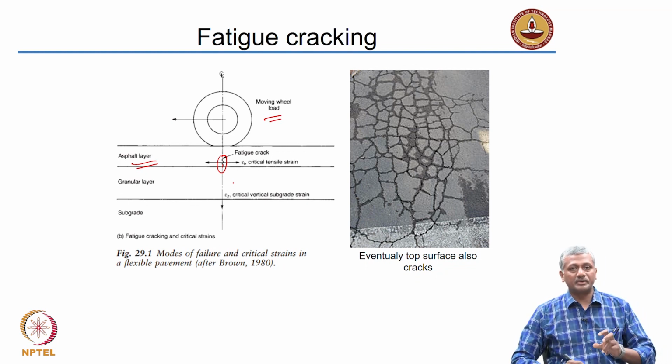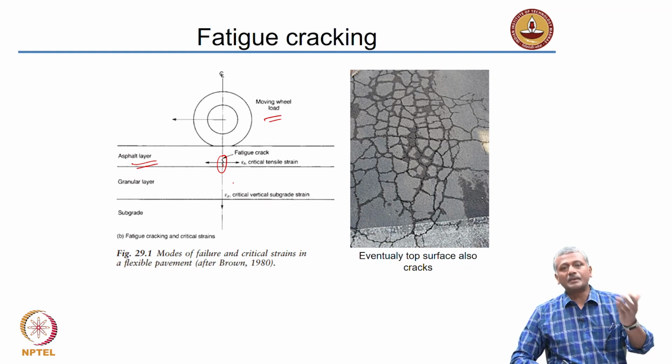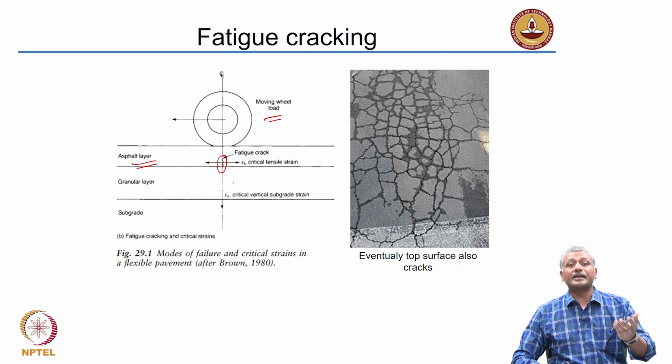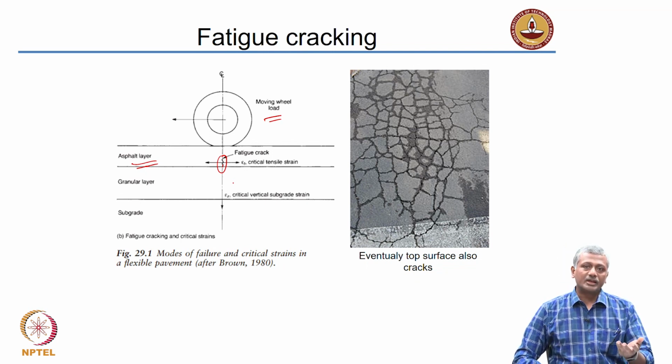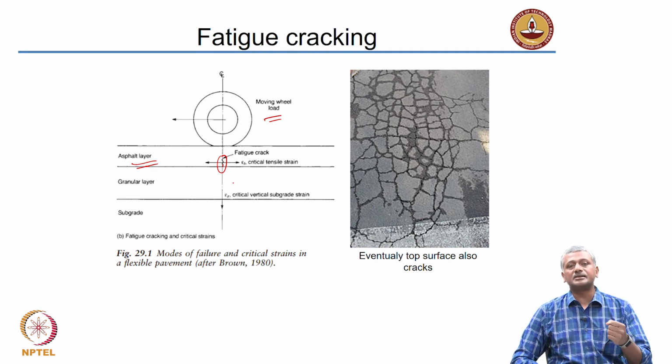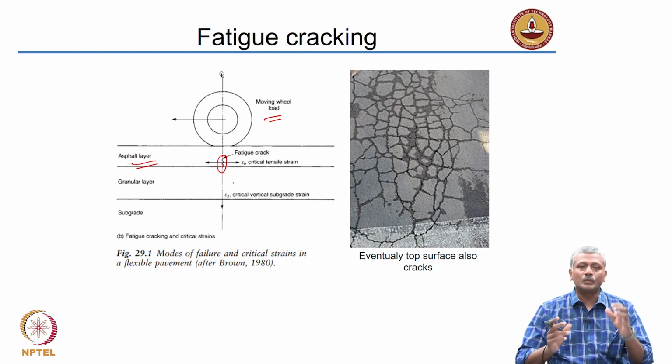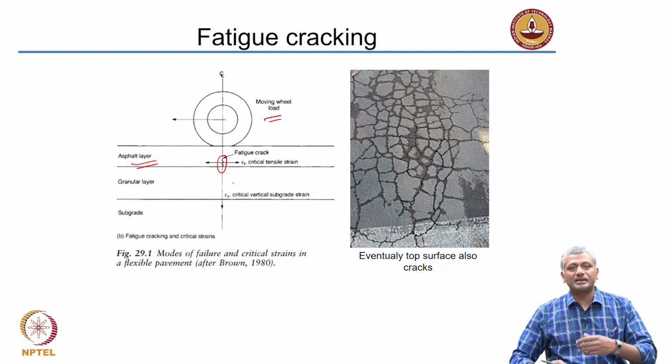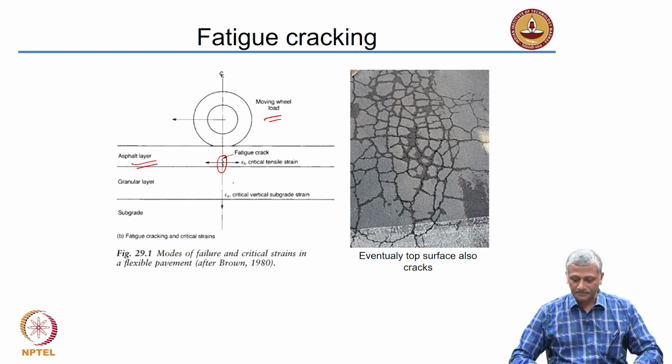So, you need to ensure that you are testing this aspect of the asphalt concrete before utilizing it in a specific pavement. Also, the needs of the asphalt concrete will obviously depend on the type of pavement that you are making. Is that a national highway? Because there we expect all kinds of vehicles. The heaviest vehicles will be there, and you need to consider the tonnage brought in by the heaviest vehicles and convert that to the equivalent number of units of vehicles that will pass over that given cross section in a certain period of time. Based on that, you need to select your material properties in such a way that it is able to match the requirements of that particular road.